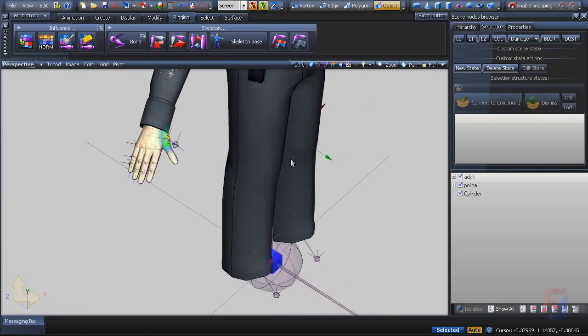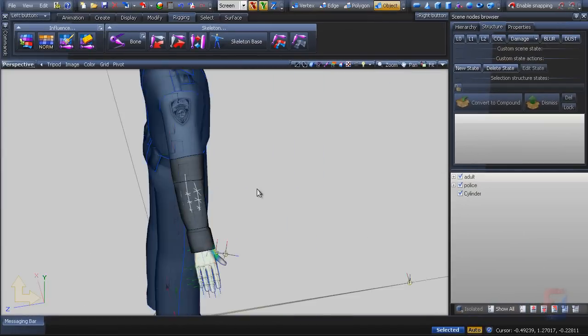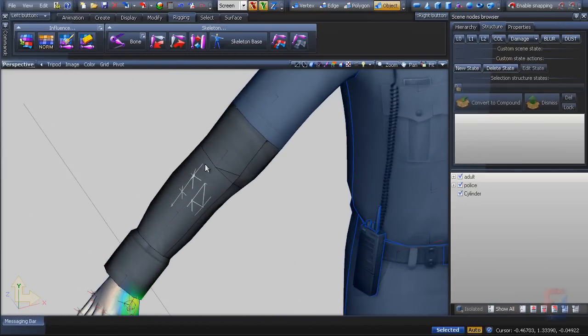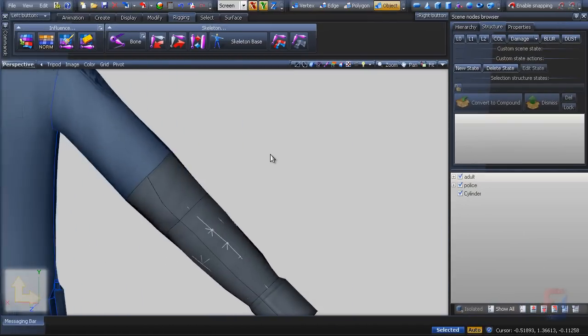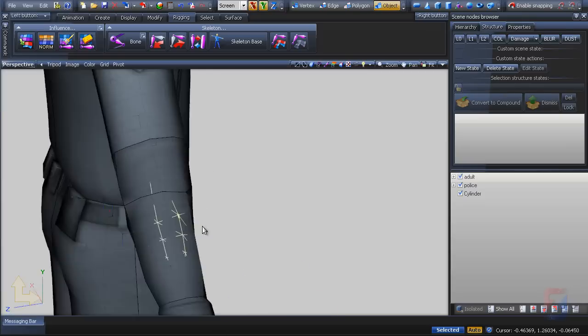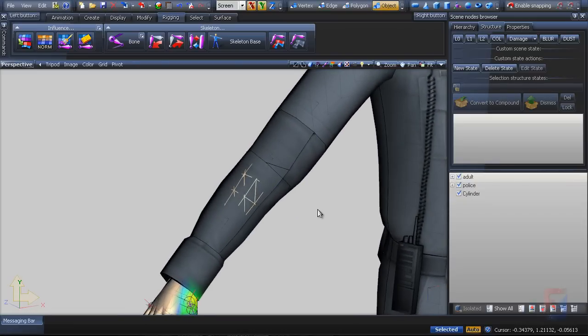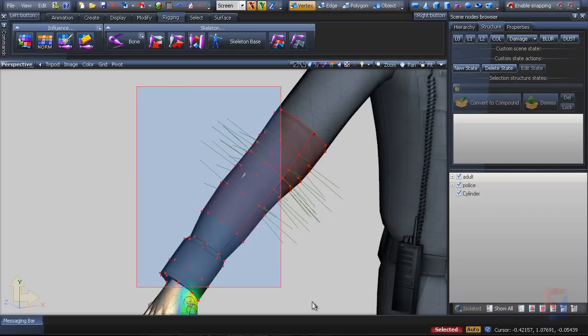Right-click on skeleton base, and pick Bones, Reset Transform. The wireframe outline mode shows solid lines across the sleeve. I've used the insert tool in sharp mode by mistake, the vertices are disjoint there, and produce improper shading. It will be fixed now. Switch to vertices level, and select the problematic area. Or an entire sleeve, for reliability.